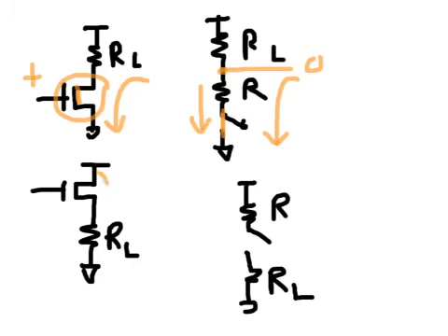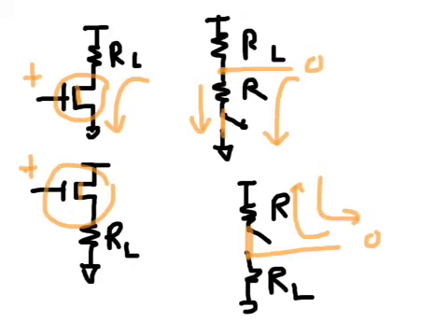Whereas in this configuration, the MOSFET is known as a pull-up device, because the application of positive voltage here forms the channel and closes the switch, and the output node here is then pulled up to VDD because current then flows to the output from VDD. However, both devices do not perform similarly.